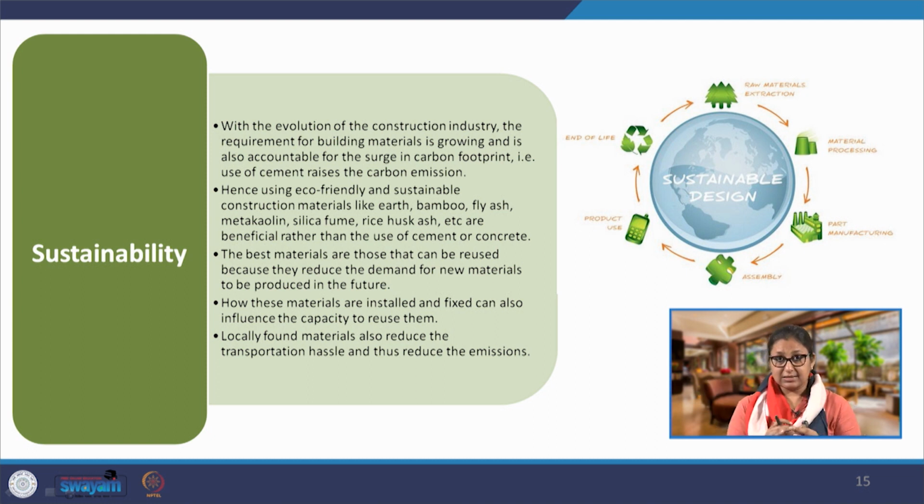When I say this, I am giving you two extreme examples of CSEB versus glass, and I clearly say that from an environmental point of view, when we say sustainability here, we are talking about environmental sustainability largely. We are not taking into consideration the other factors, because you cannot absolutely discard a material like glass. It comes with a lot of benefits, for example, daylight and connection. You can't just block the entire wall using CSEB just because it is highly environmentally sustainable. We will still have to use glass where glass is required, but how much?